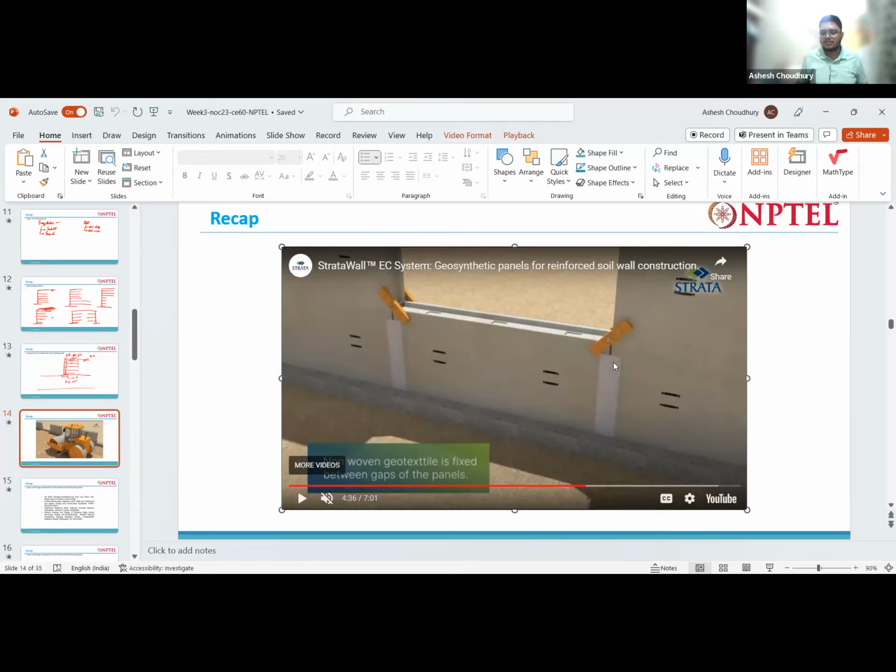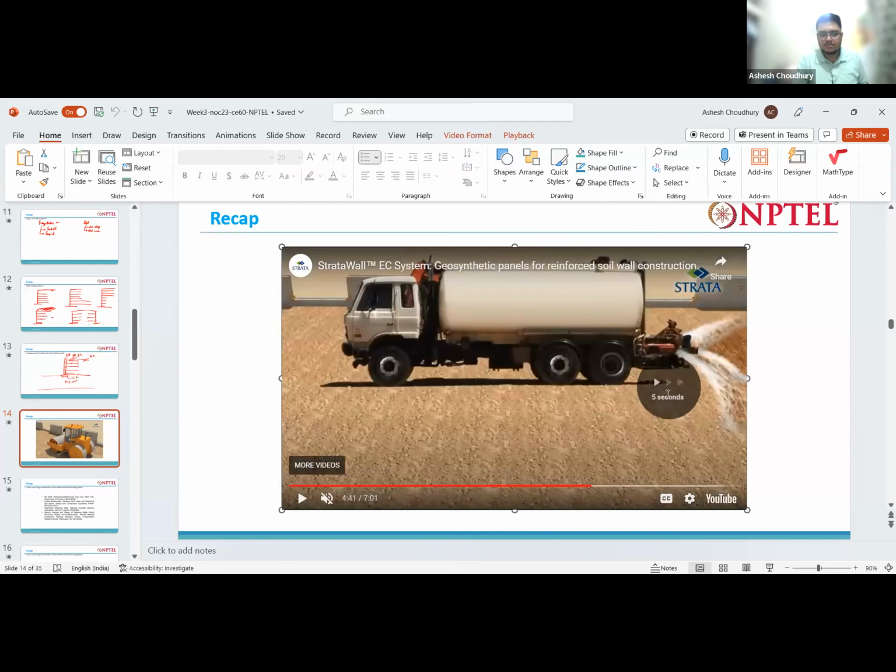After the soil is put over it, this is obviously going to stay in place, right? So even if the glue wears out, this will stay in its place. We glue some geotextile in this joint so that the soil does not go out of this joint. If you do not put that, little by little the soil will keep coming out of these gaps, and as time passes, a large amount of soil will come out and form a slush outside. It looks very bad. That's why, and also for erosion prevention, this is good.